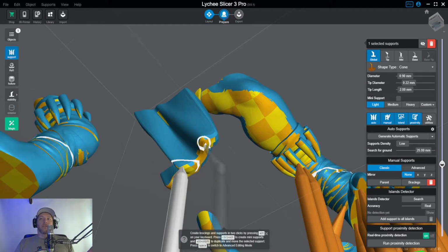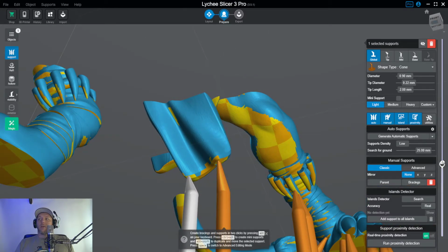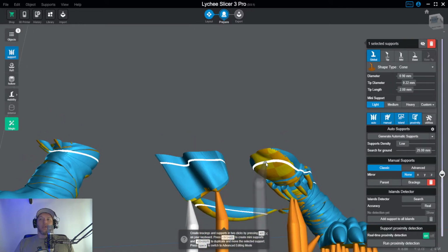But if our supports are too light in these areas, and the build plate's trying to pull this off the FEP sheet, that pull is pretty strong.